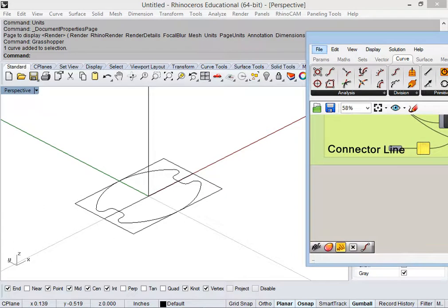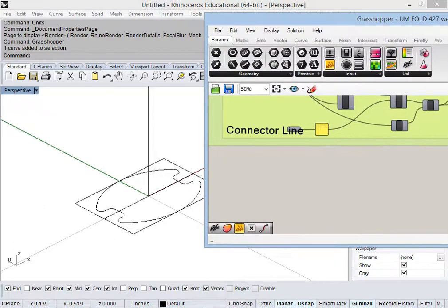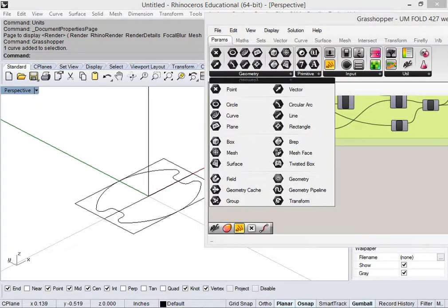Under parameter, there are all these different geometry containers. In this case, this would always fall under curve geometry. You can use curve geometry for everything, right? We talked about this. A line is a curve, but a curve is not a line. So curve will always work with 2D line work.